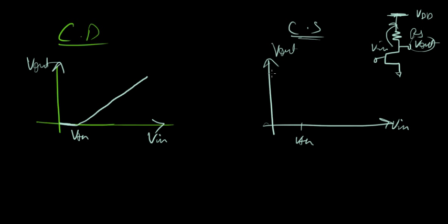That's it. So we're starting from here till VTH, and when V in crosses VTH, the transistor turns on, and there's a current driven through this impedance, right? So then your V out starts to fall, right? Remember this diagram from before? So just look at these two. It's a beautiful comparison, isn't it? So it's great to know.